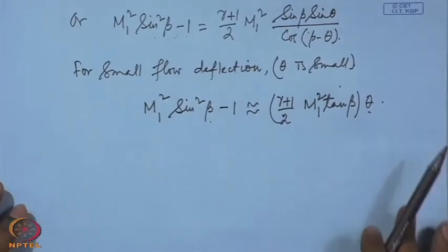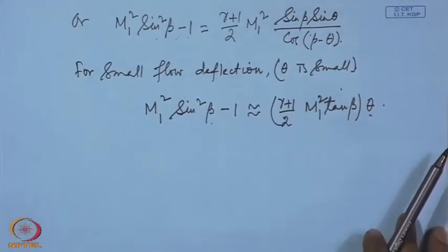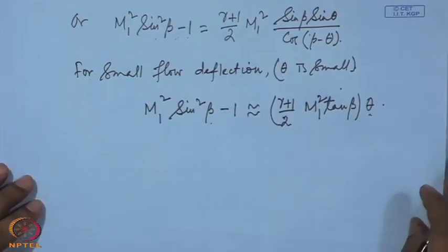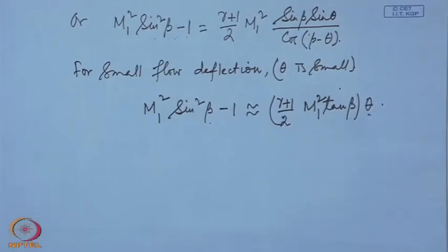So, these are the basic relationships that are required for oblique shocks, and with knowing about this oblique shock, we will now first try to construct our first example of supersonic flow, that is, supersonic flow over a wedge. For this we will use the basic concept of inviscid flow, that is, any streamline in inviscid flow can be replaced by a solid boundary.